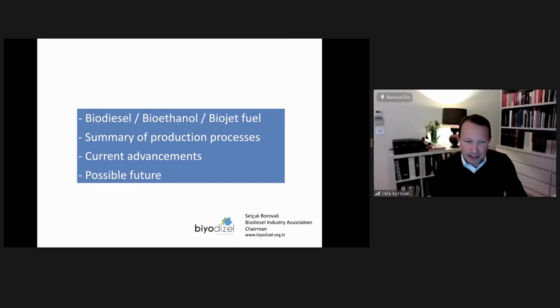Initially, it was easier and served more control functions. But as time goes by, the batch reactors are not serving the high capacities, and all the industry transformed to continuous production. Once you feel quite confident on the production, and especially if you remember, I emphasized the recipe formation, the feedstock mix, then you can start feeding your continuous reactor. But one thing to be careful about: once you start feeding the continuous reactor, it is a pipeline. It just carries on, and there is a risk of ending up with a low quality product. So usually this is how most of the industries start.